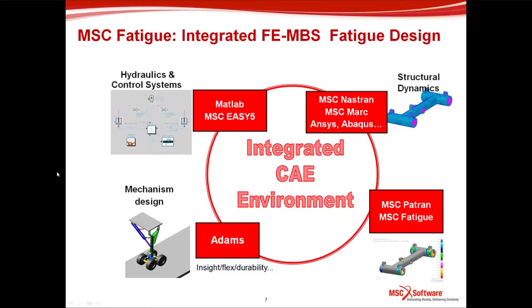The concepts are well understood, but obviously it's very important that the user experience and the capacity for the user to seamlessly pass information from different tools that are used in the CAE arena. You can see here that you would have FE codes such as Nastran, Abaqus, or Marc, and ANSYS and so on, or you will have multi-body dynamic solvers or system analysis and control system, and they all need to be connected strongly. And of course, the fatigue product should be in the loop and not in a dead end as a sort of post-processing exercise. In fact, MSC Fatigue is a bit special in that sense because it sits inside Patran, so it's entirely within an FE GUI environment.